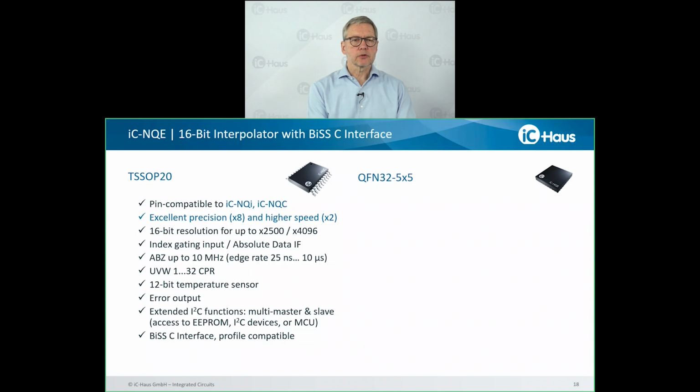I2C allows you to access the external EEPROM and other I2C devices, and that is the preferred interface to connect an embedded MCU if there's any. The BiSS interface is profile compatible. It allows you small CRCs and longer CRCs, things which are quite typical.